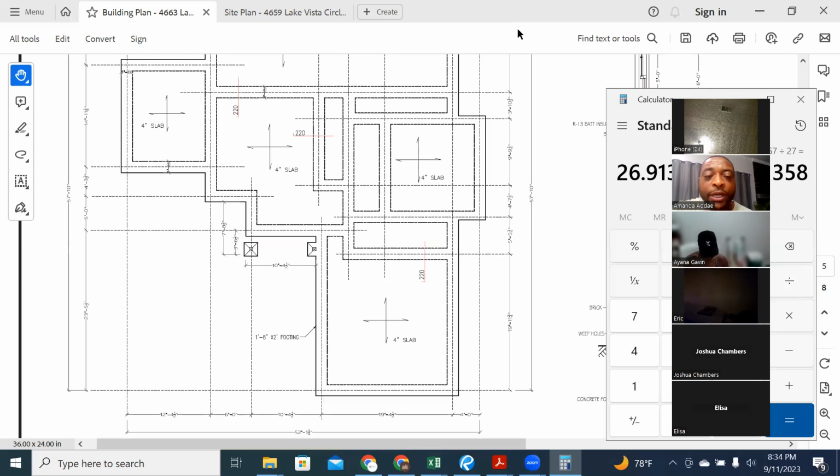For us who are on site, we're working this backwards, but it makes perfect sense. It's exactly on point. So that means that our footing was dug damn near perfectly because it meets exactly the criteria that we're given, which will calculate how much concrete we need. So before they went out to order the concrete, we could have easily said, I need 3 trucks. When you call the company, they'll ask you, how many trucks do you need or how many yards? So we can say we need 3 trucks for our footings. We calculated it. We added them for a little bit extra maybe, but we're calculating that 3 trucks is going to take care of our footings.